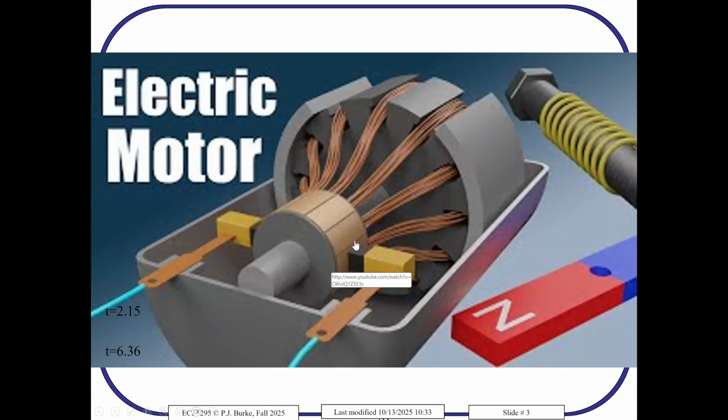And that's why it's called a brushed motor. So there's a big disadvantage, which is wear and tear. The lifetime is going to be limited by however long that brush mechanism works. And the friction. But it's very simple. So for that reason, it's a very commonly used motor for low cost applications.